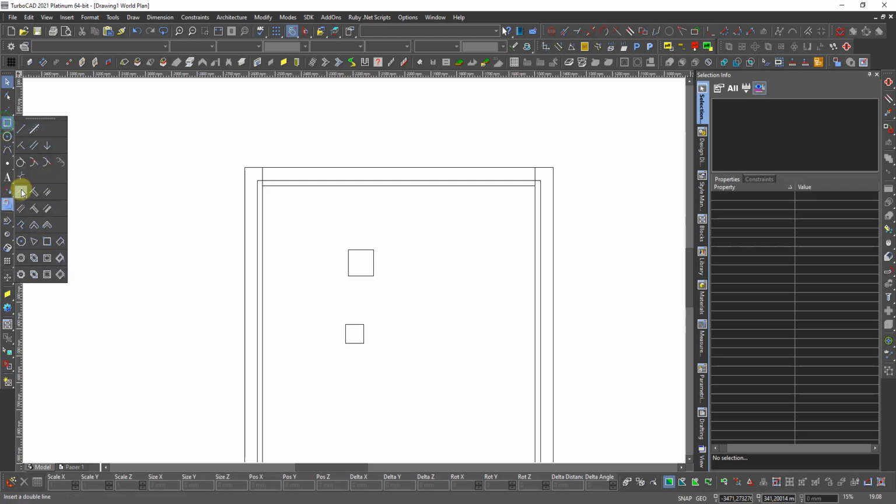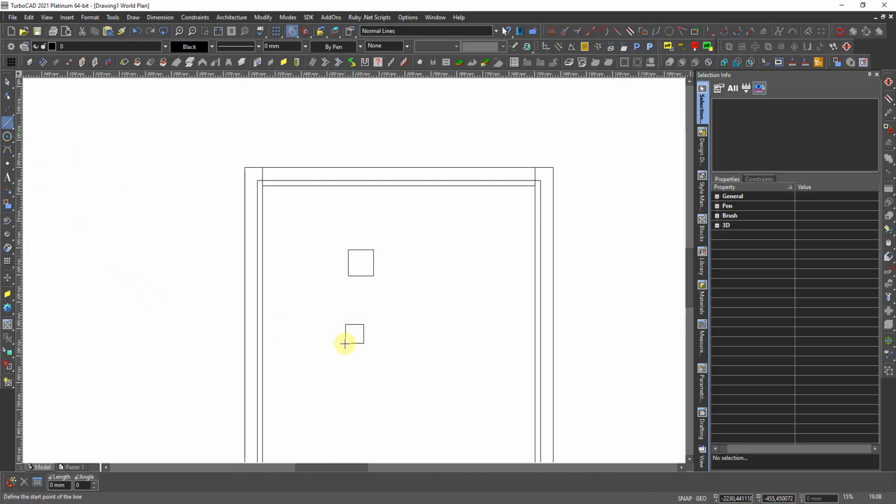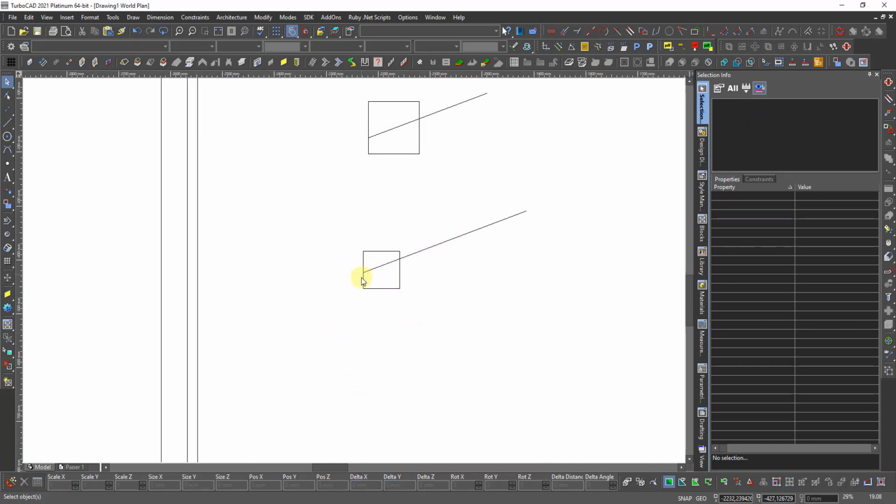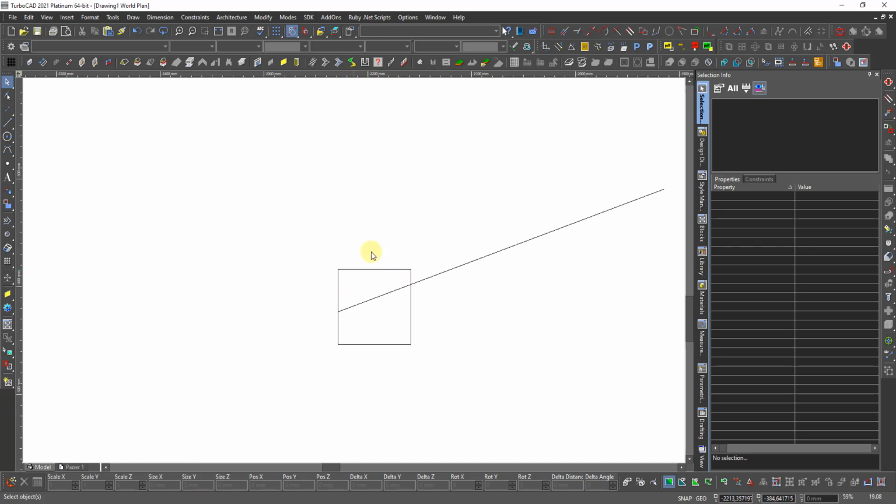And I can draw a line from this corner, from V and up. We have minimum 18 degree, so I use 20. More simple number. 20 from V and up there, and 20. I select this and I'm lifting them up 30 millimeter. Because I like this is a little bit thick in the front. It looks more massive.